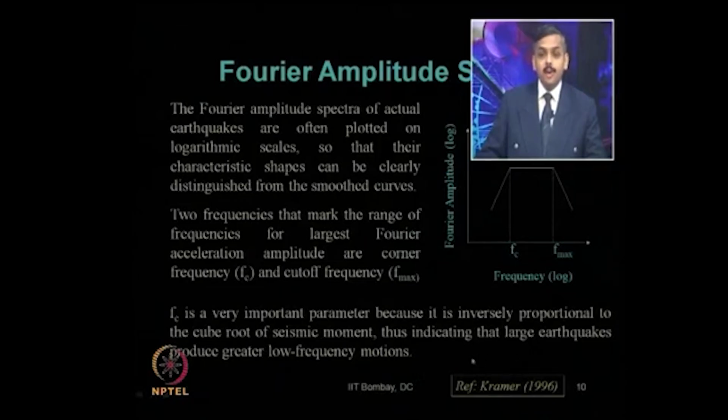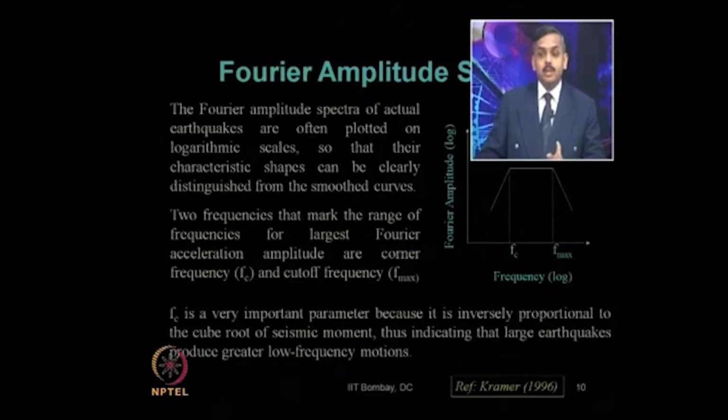So, that is the reason why we were mentioning earlier what is considered in literature as the range of frequency. As per Benjamin and associates, up to 9 hertz of frequency we should take. Above 9 hertz frequency we generally discard. Below 8 to 9 hertz frequency, whatever earthquake occurs, the peak value of the horizontal acceleration we consider as the effective design acceleration for any structural design.